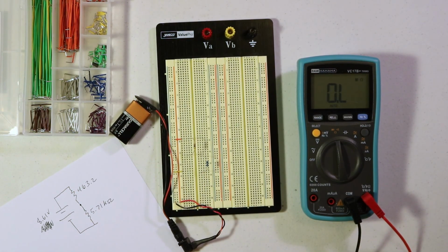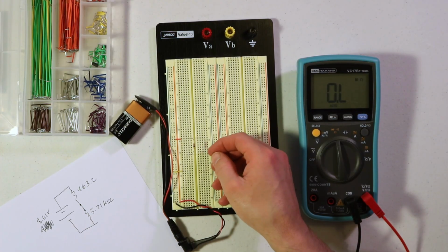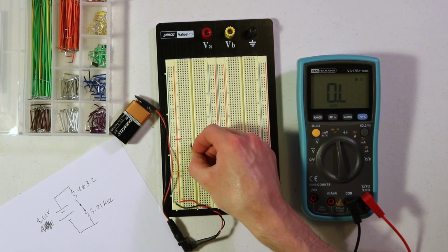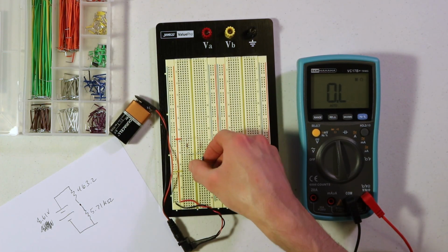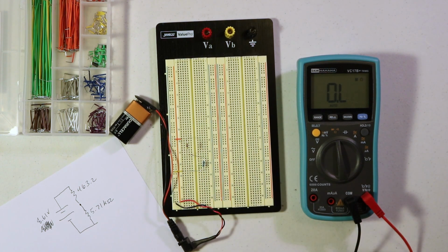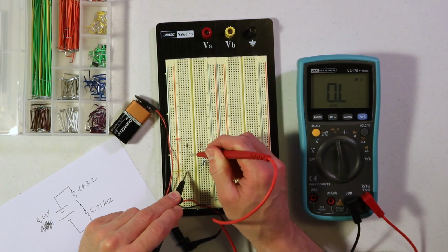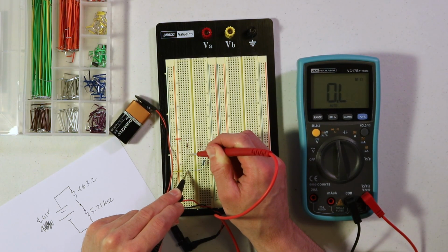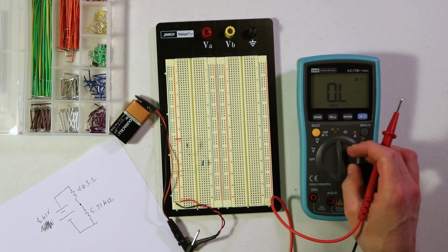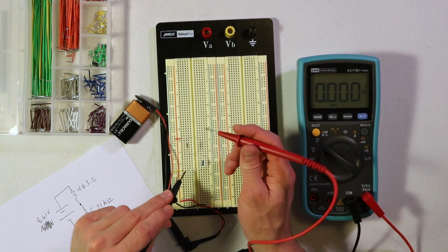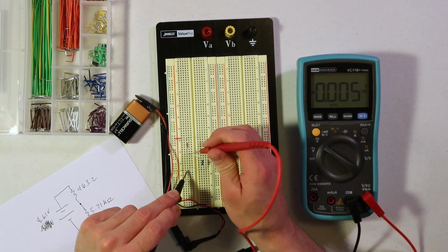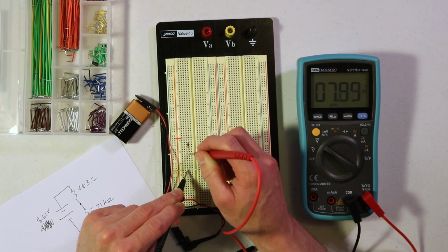463.2, and your values are probably going to be different because your resistors will vary differently than what mine were. Alright, so let me put that back into the circuit now, and let's check the voltage again. So from here to here, across the 5.1 kilo ohm resistor, that was resistance. I have to switch it back to voltage, so those are things you want to remember. Don't forget that. It's easy to forget.